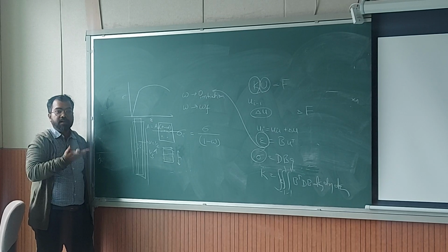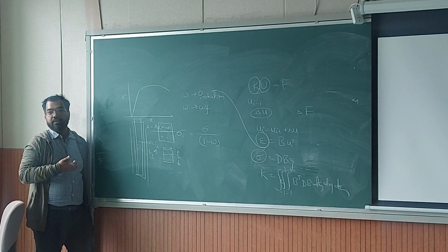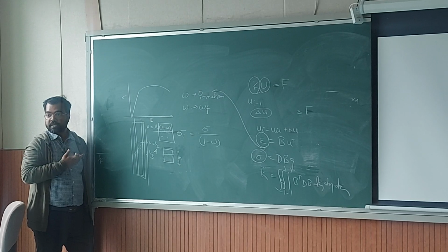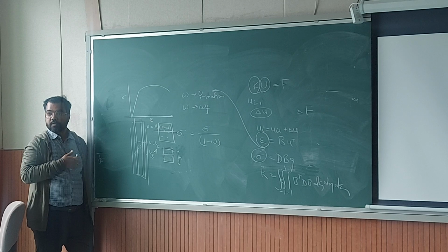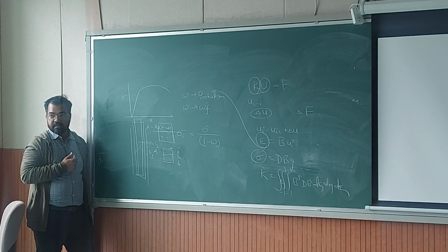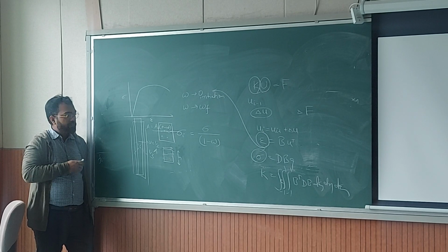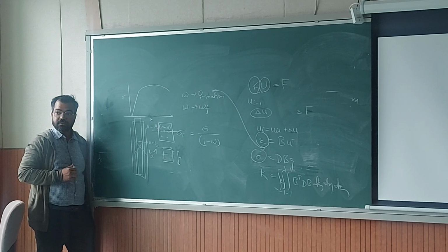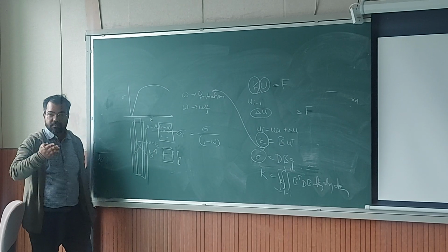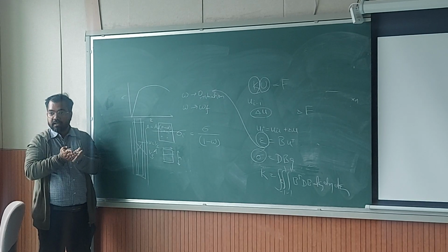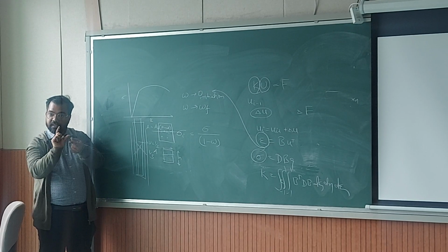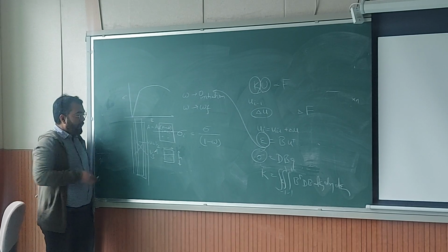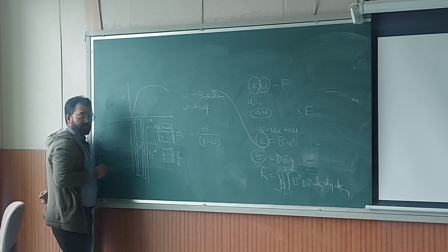So between sigma 1 and sigma 3, you are going to have maximum shear stress. Along that direction, you are probably going to have maximum shear strain. So maximum equivalent plastic strain. And the damage will initiate on these regions. And this region is not rectangular, it's a cylindrical specimen. So you have a conical shape where damage will initiate.